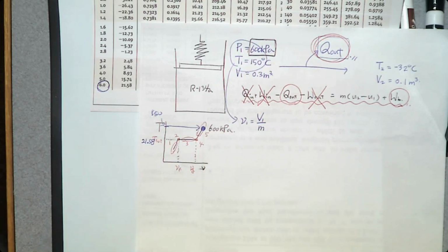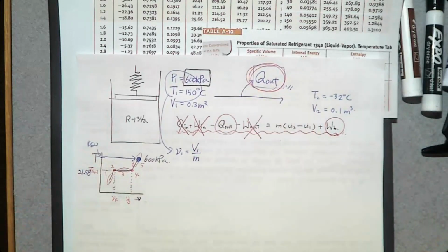So we have superheated vapor in our system. Throughout this cooling process, now we only have superheated vapor at the initial state. We have no idea about the final state. So you have to re-evaluate the phase change process at the end of this cooling process.